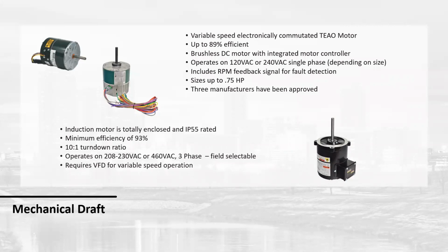3-phase motors are high efficiency induction motors. Those are off the shelf Marathon 3-phase motors. High turndown, 10-to-1. We do use an external VFD. But the best news for the end user is that this is an easily sourceable motor. So if anything goes wrong, typically it's going to happen on a Friday afternoon about 4:30. And considering you guys are 2 hours behind my warehouse, you'd have to wait till Monday to get a motor, or you can just go down to your local motor shop, have it rebuilt or replaced, and have it up and running that night.